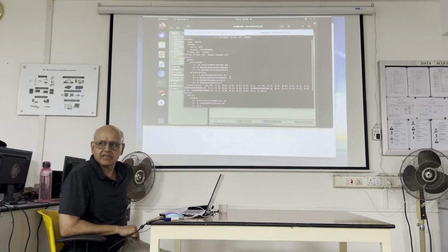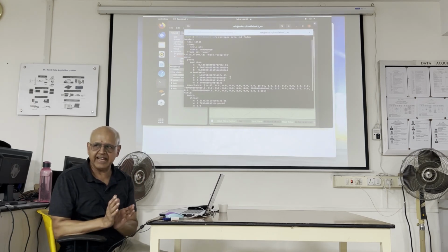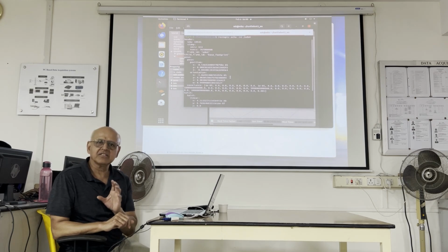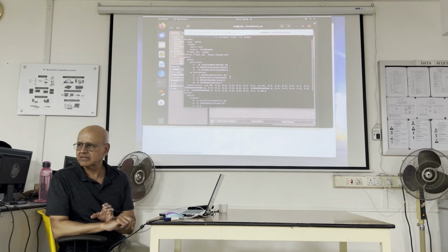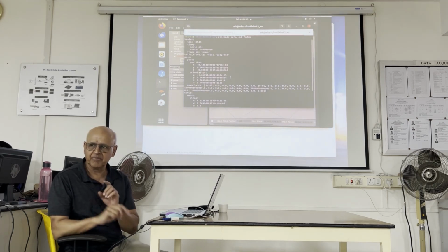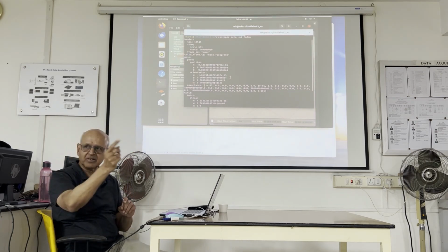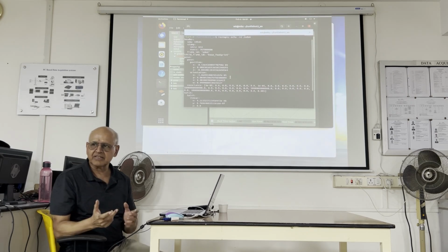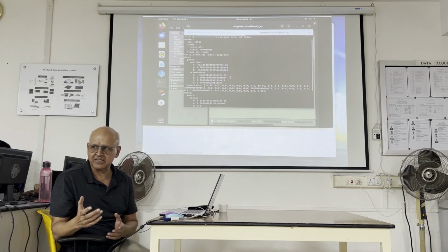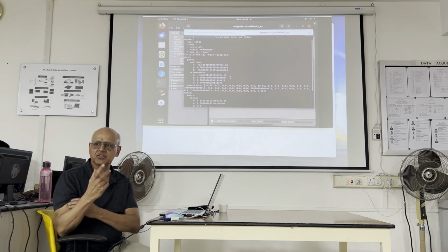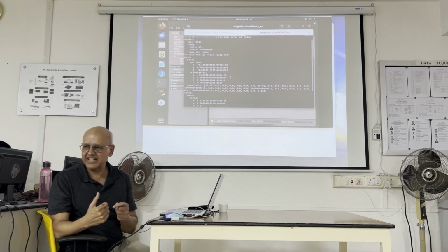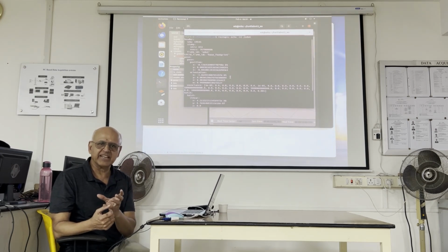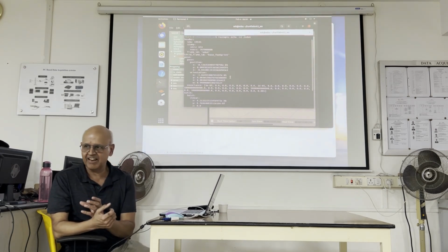Normally you would expect a single heading angle, right? But there are 4 numbers. It's because angles are very troublesome in robotics. Angles have this problem that when you go all the way around, you get back the same value, right? So in other words, 370 degrees is the same as 10 degrees. There's also another problem known as gimbal lock. In 3 dimensions, you can get the situation of gimbal lock, G-I-M-B-A-L lock.